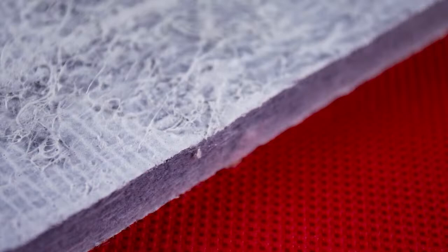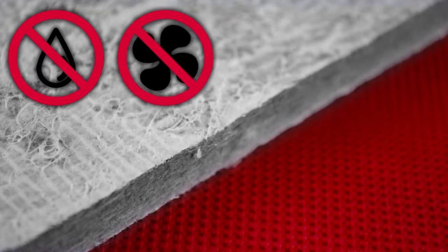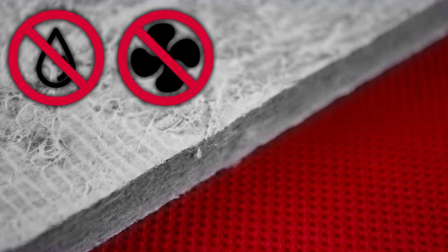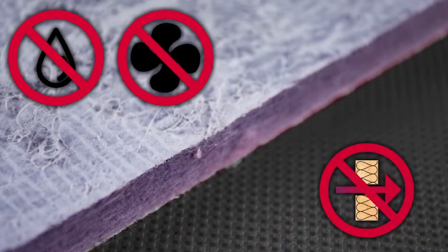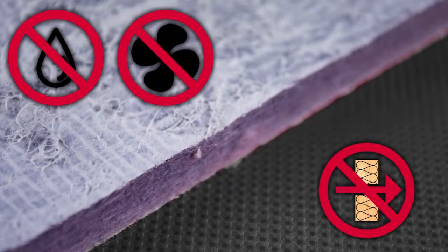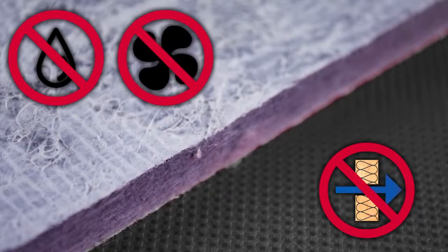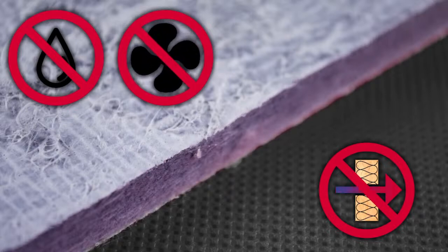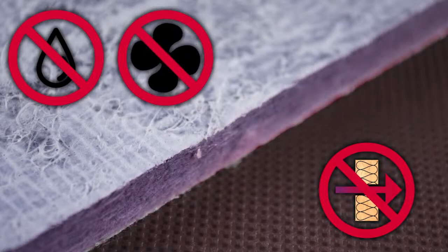As well as protecting the existing building fabric, Raptherm's hydrophobic properties provide a secondary barrier to water ingress, and by sealing tightly to door and window frames and other penetrations, also limits heat loss associated with air leakage. The unique layer of aerogel insulation in the Raptherm also effectively limits cold bridging by providing a continuous insulation layer across the back of the facade, so there's a thermal break between the new structure internally and the cold outer stonework, providing a further boost to the energy performance of the upgraded building.